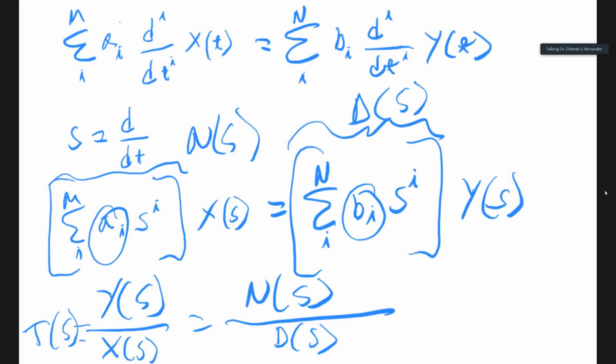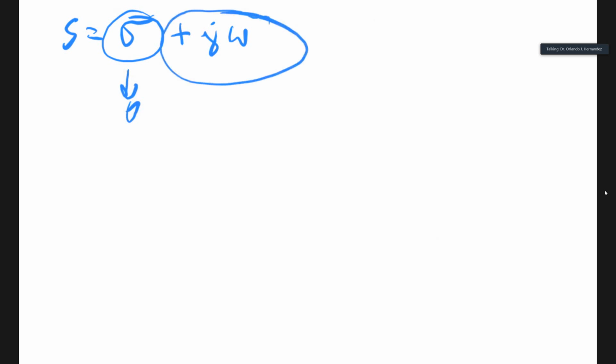Now we go further, because if you recall, the Laplace transform expresses all the behavior of the system, both transient and steady state, also known as phasor behavior. Recall that S is sigma plus j omega, but if you solve for the response at the Laplace transform level, this sigma shows up in the decaying exponential. So that is transient behavior. That's why we get away with setting that to 0 and focusing on j omega, which is the steady state behavior, the frequency response.